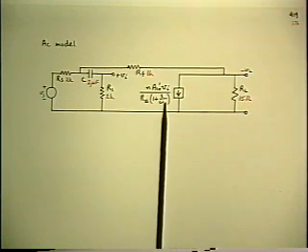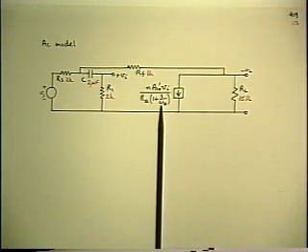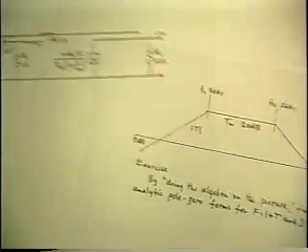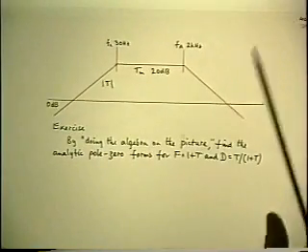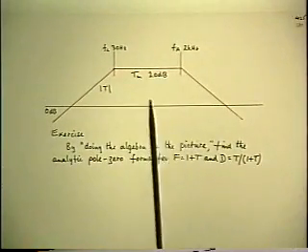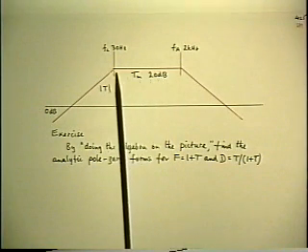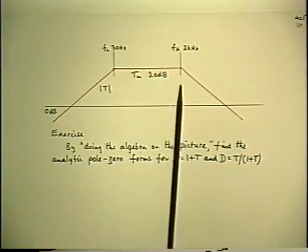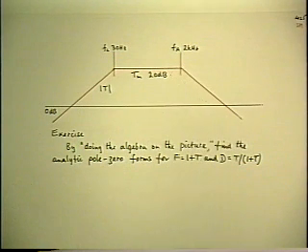and then you restore at the same time the normal pole, which is part of the forward path, and that pole is at 2 kilohertz. So the result is that the loop gain has a mid-band value which is 20 dB, an inverted pole at 30 hertz, causing the gain to drop off below that, and a normal pole at 2 kilohertz.